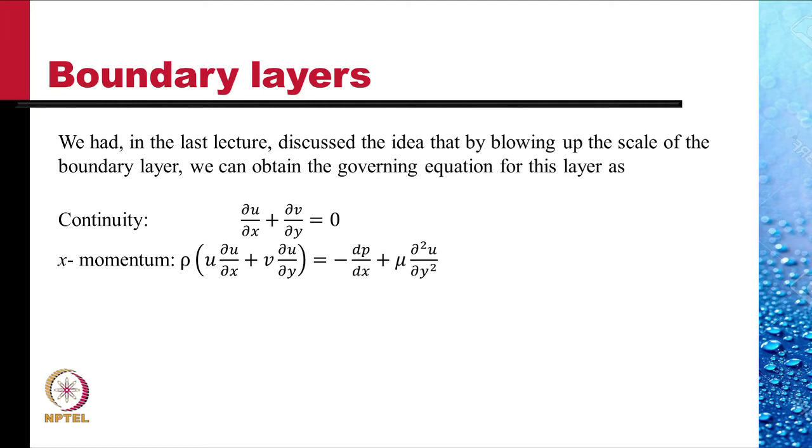Notice that we have been able to retain the viscous term ∂²u/∂y², but the viscous term μ ∂²u/∂x² is still negligible.